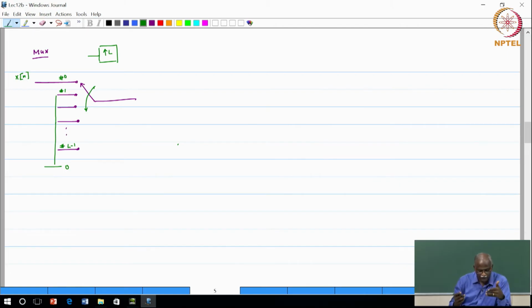Now, very often we also want to reconstruct the blocks. So, if you remember how the blocks were coming in after the blocking operation, we said that it was x0, x1, x2, and then at the next instant of time it will be x3, x4, x5. So, basically blocks of data are coming in. If I wanted to reconstruct, then with the interpretation that we are looking at, you do an upsampling operation, okay, that will make sure that you are inserting the number of zeros appropriately.